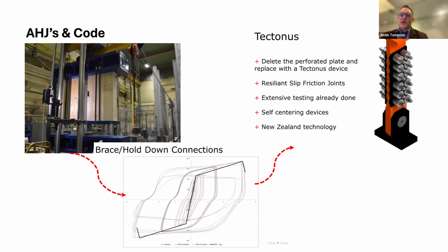They come out of New Zealand, largely driven out of the experience that they had with the Christchurch earthquakes years ago. And they are a tested product that allows for, in the brace frames and the shear walls, to absorb shock and then actually be able to right the building as well. So those actually went into the building in lieu of redesigning the shear plates. So that became part of the tender package.